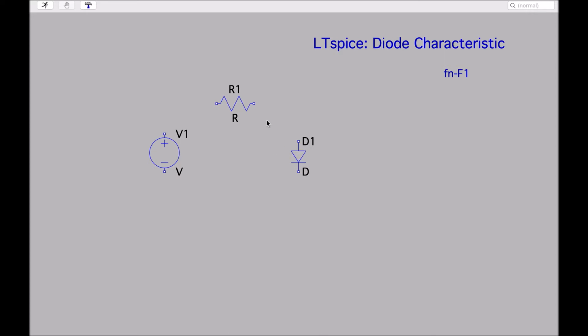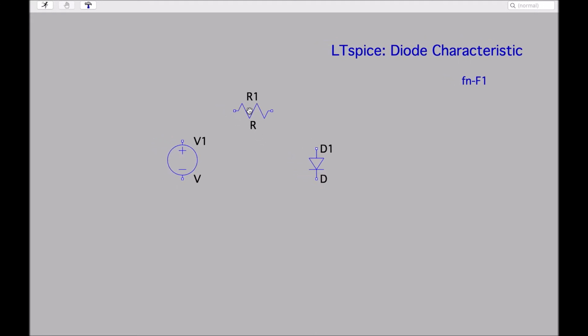One thing to mention at this point is we can move components with another function, which is the F7 key. If we press F7, you'll see the cursor changes to a little hand, and we can then pick up and drag around components and place them again. That little hand remains to move components. I need to press Escape to get back to the normal cursor again. So if you do want to move components, you can use that F7 function. And if you want to rotate components, you have to have picked them up with that F7 function first.